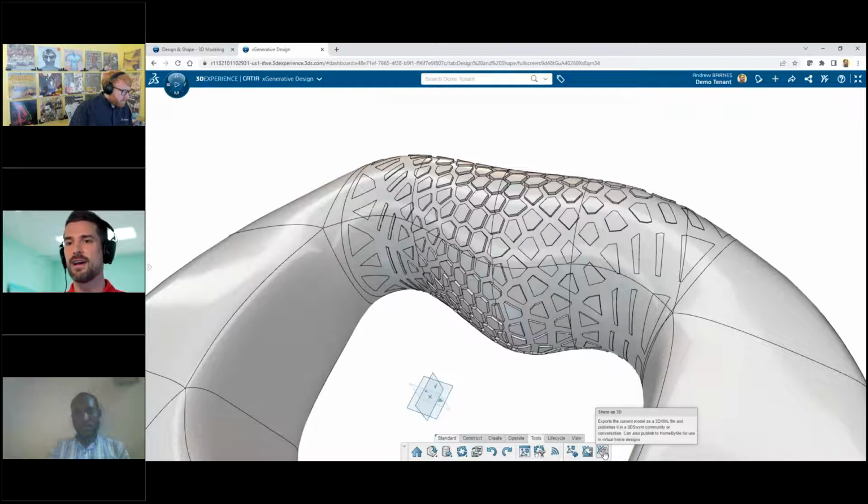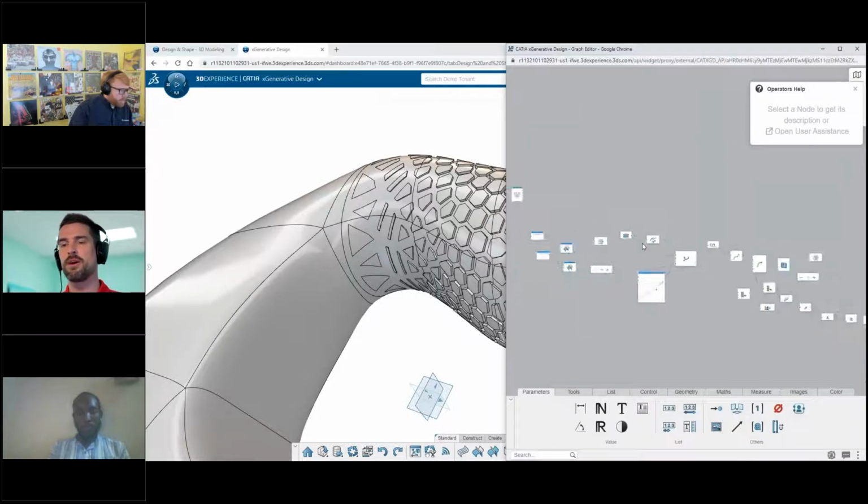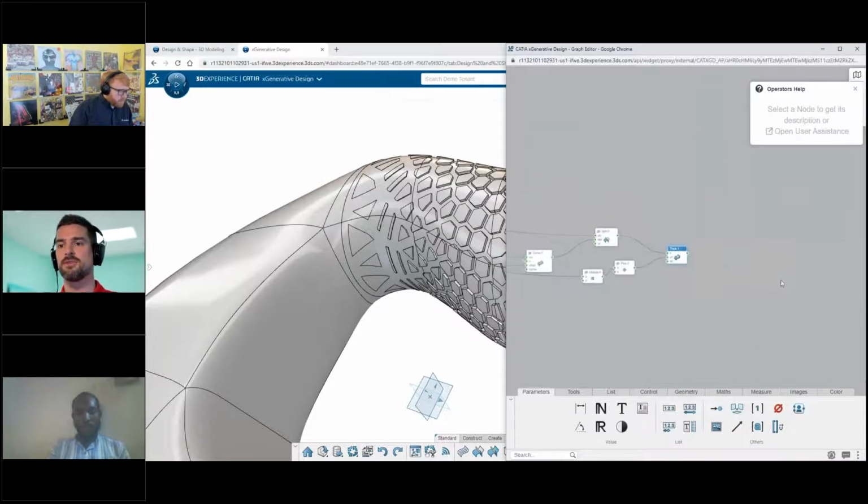A lot of the time, the sacrifice with those other applications out there is that they create tessellated geometry that can be 3D printed, but can't be brought back into 3D CAD very cleanly and shelled out and prepared for manufacturing, or, like Andy said with the woven basket, thickened and prepared for an injection molding process or something like that.